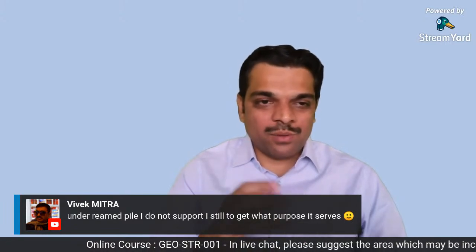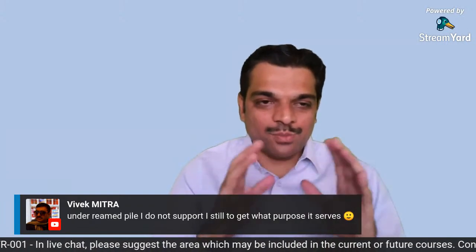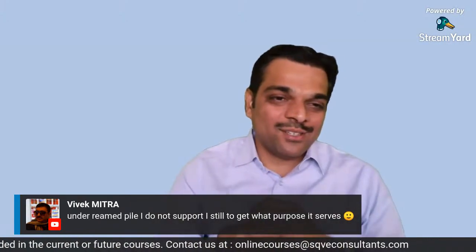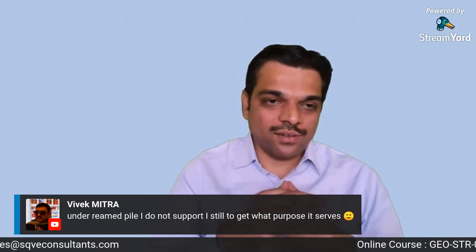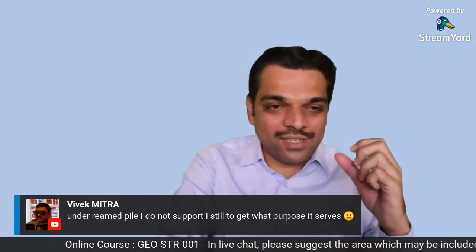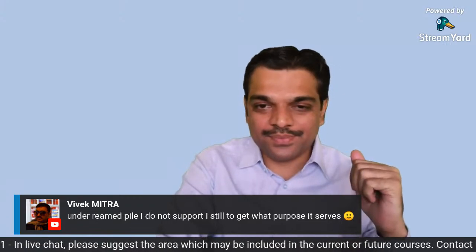So there were a few experiments done actually. The bulb was prepared as per the execution or as per the drawing, and then those piles were actually pulled out. And then it was virtually seen that there was no bulb. It was a very partial bulb which was formed, right? So it is not going to serve the purpose for which it is being used. So I agree with you, yeah.